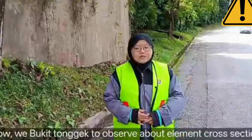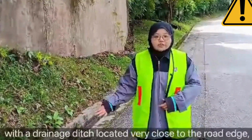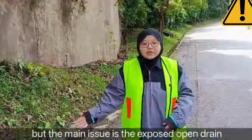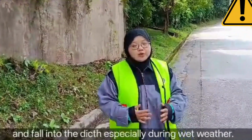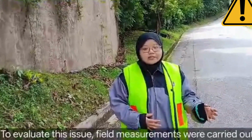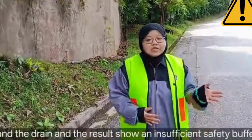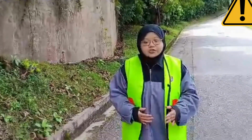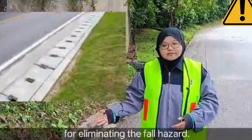Now we investigate the cross section element. The cross section consists of a narrow shoulder with a drainage ditch located very close to the road edge. Although the road width is sufficient, the main issue is the exposed open drain with no protection barrier, where a vehicle may easily lose control and fall into the ditch, especially during wet weather. To evaluate this issue, field measurements were carried out to assess the distance between the carriageway and the drain, and there is an insufficient safety buffer compared to standard road design requirements. Therefore, the most suitable mitigation is to convert the open drain into a covered drain to eliminate the fall hazard.